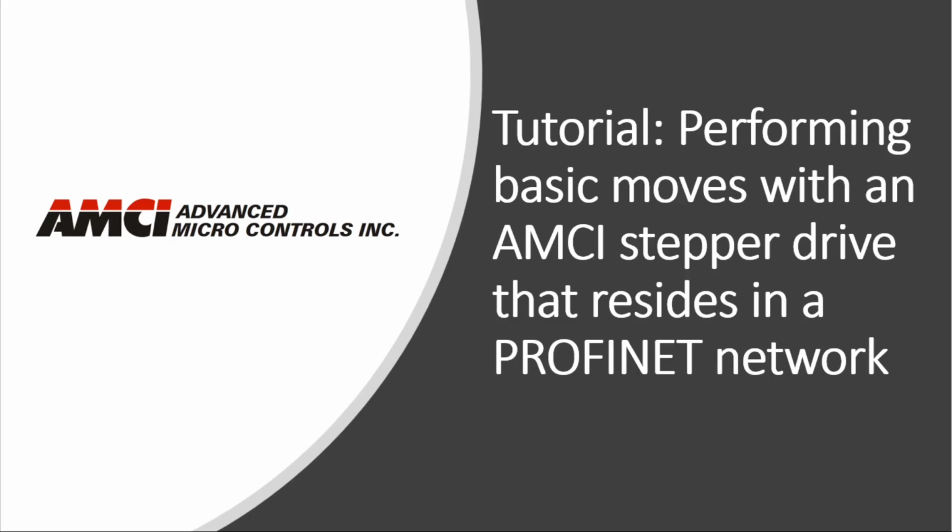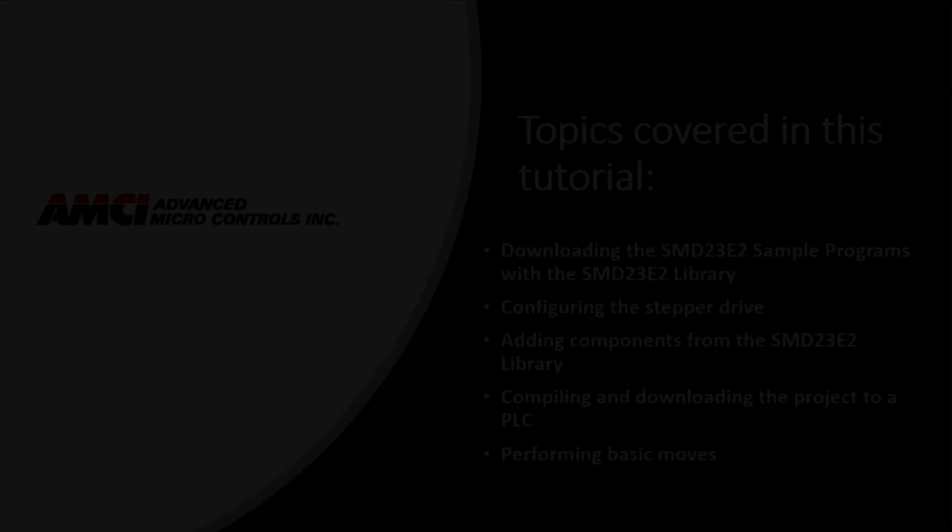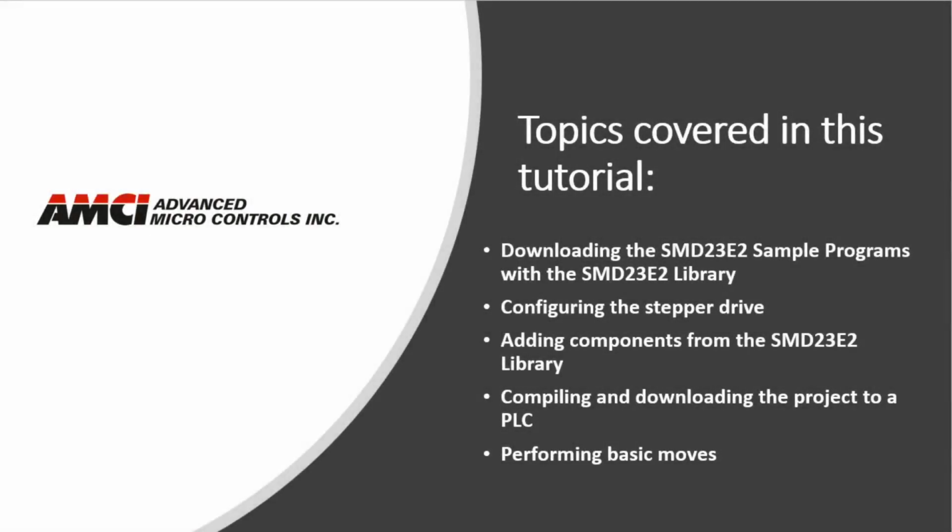For this tutorial, we will use this SMD23 stepper drive as an example, and this tutorial is applicable for all of our networked stepper drives. These are the topics that we will cover in this tutorial: downloading the sample programs with the library, configuring the stepper drive, adding components from the library, compiling and downloading the project to a PLC, and finally performing basic moves.